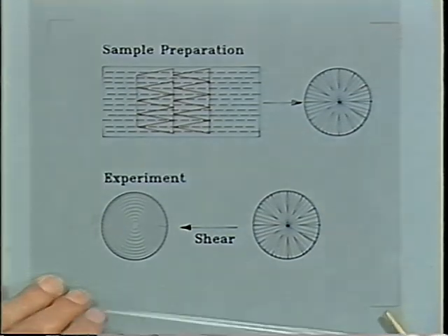And that's where those cylinders are positioned. And we want to know now, how does the structure go from this initial order to the final order? Again, we will use small angle X-ray scattering to probe the structure at intermediate strains. Now, in this case, the sample will be sheared and rapidly quenched. The shearing will occur at 140 degrees so that we can deform the sample fairly easily, and then quench it